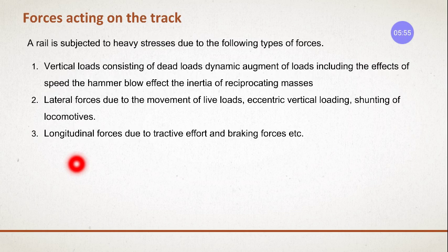The longitudinal forces, longitudinal means along the length of the movement of the train. When the train tries to move over the track, these forces are applied. We have to overcome the frictional force and the inertia force. When you apply the brakes also, there are forces applied over the rails or track. So these are all the forces that act over the track.